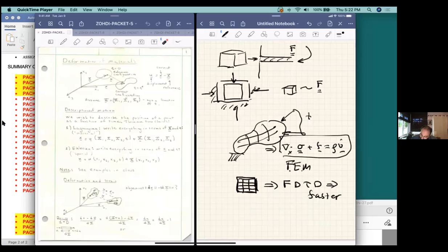So oftentimes, if the deformations are small and the geometries are regular, these types of methods are preferred, and there are a variety of different reasons why, but primarily the meshes don't get distorted. And if you have objects where things start to change in their shapes, for example, change in different configurations, the finite element method is uniquely adaptable to this kind of a configuration, but costs a lot more than the finite difference method. So it just depends upon really what you're after. You'll find that finite difference time domain methods are usually used for linearized or small deformation problems, wave propagation, things where the body doesn't distort a lot. But for manufacturing, almost universally, it's finite elements.